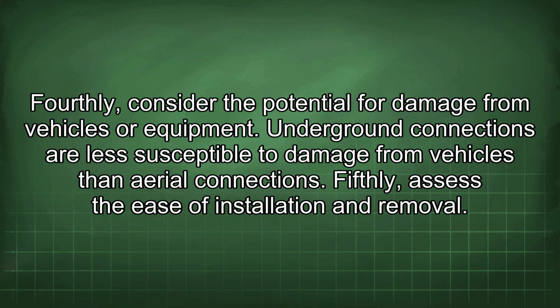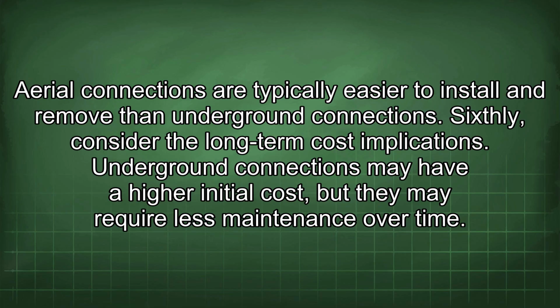Fifthly, assess the ease of installation and removal. Aerial connections are typically easier to install and remove than underground connections. Sixthly, consider the long-term cost implications. Underground connections may have a higher initial cost, but they may require less maintenance over time.